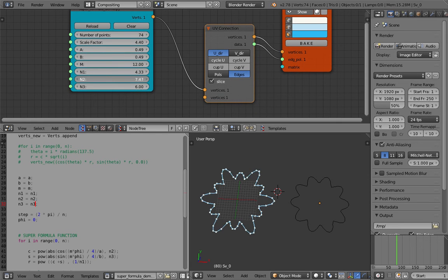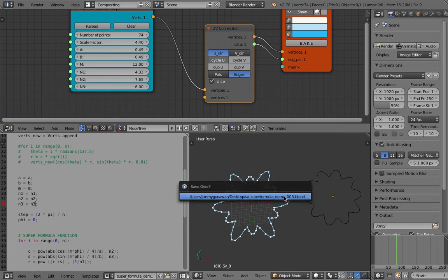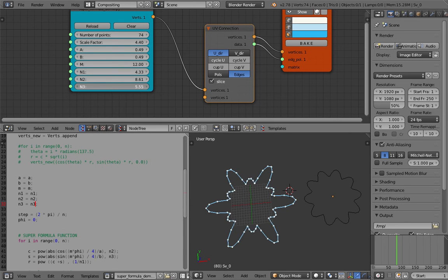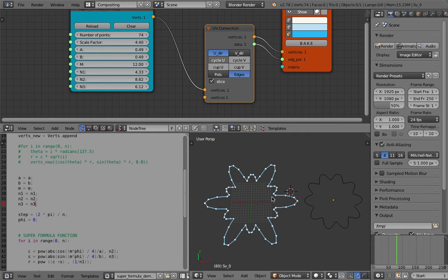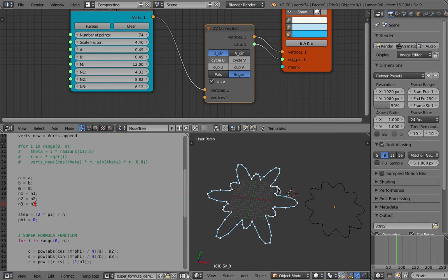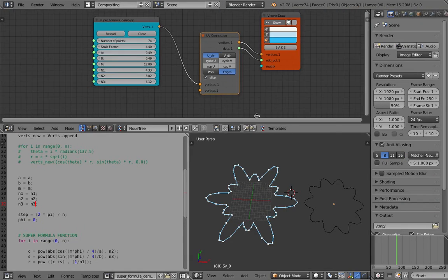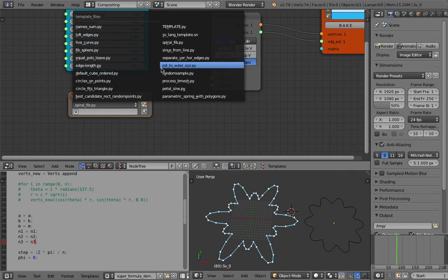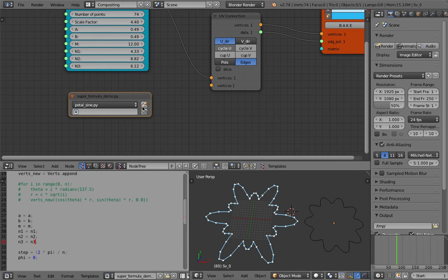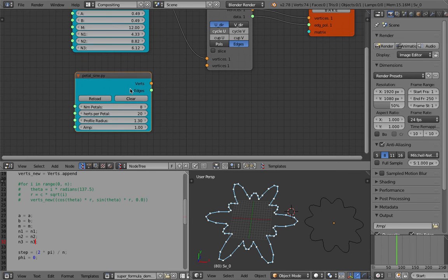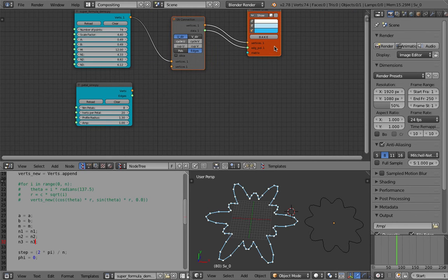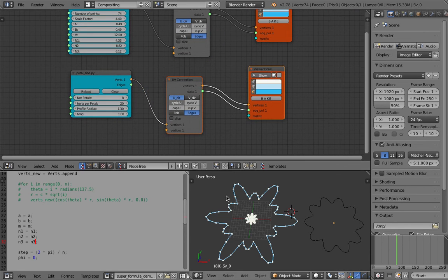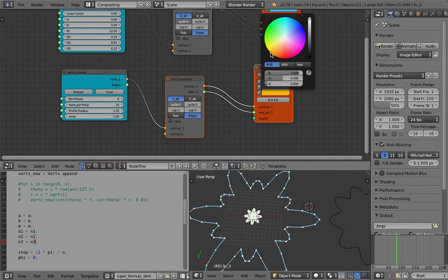And then we have the N. So this N gives more control over the petal, and that petal and that petal. So we can think of it like, okay, the super formula in this case is more like a flower petal formula. I keep saying petal formula. It's another script node. If we just get it from here, this comes with Sverchok, petal sine, and then if we load it and get it, I'll create another of this thing and plug that in there. So this is the other formula that comes with Sverchok.